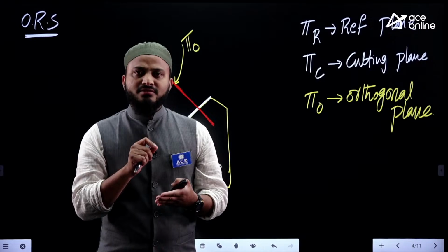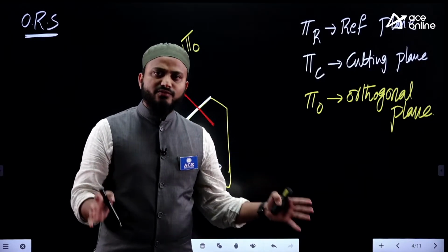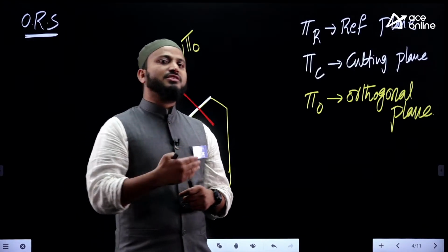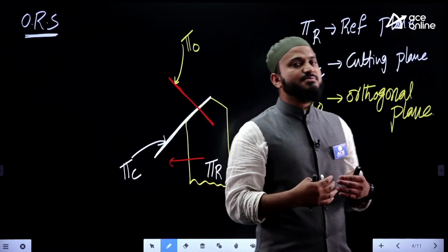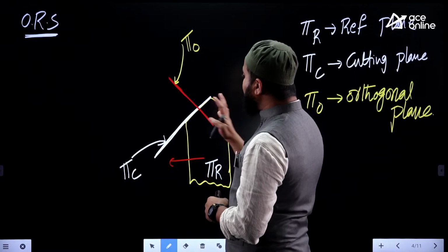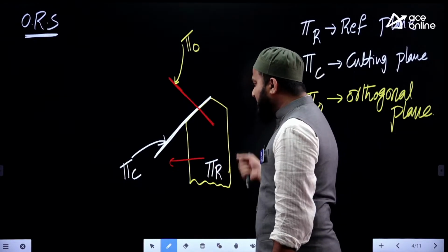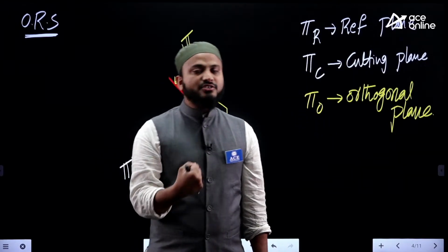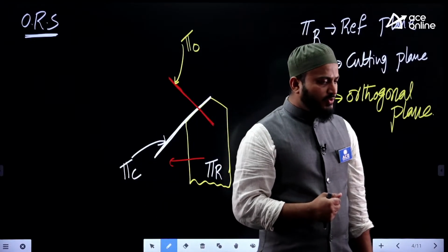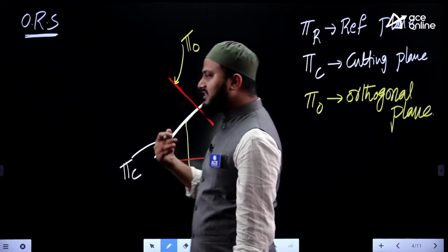So the initial two-dimensional analysis helps us to estimate the cutting forces, shear forces, frictional forces, and after that, all the velocities also come on the same plane. Based on those forces and velocities, we are able to calculate the total power. Once we have the estimate of how much total power consumption is required, we then adjust the tool geometry in such a way that we always have minimum power consumption. Minimum power consumption is always a basic objective of any topic or any subject you take.